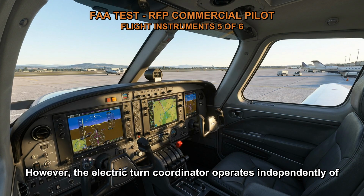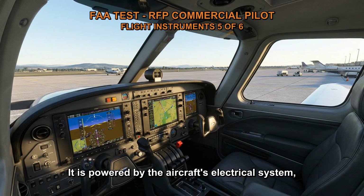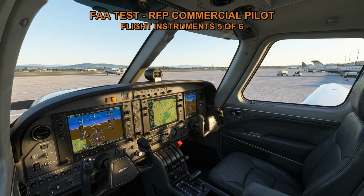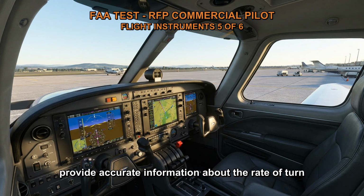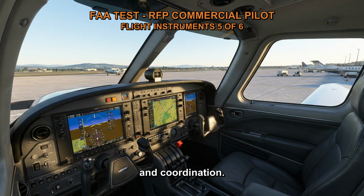However, the electric turn coordinator operates independently of the vacuum system. It is powered by the aircraft's electrical system, typically utilizing solid-state gyros. This means that even if the vacuum system fails, the electric turn coordinator can continue to provide accurate information about the rate of turn and coordination.